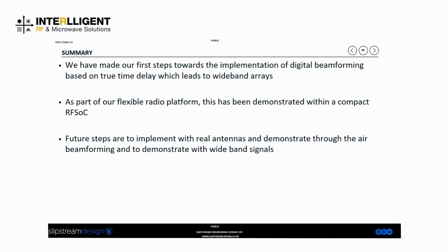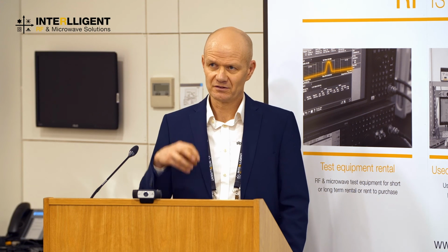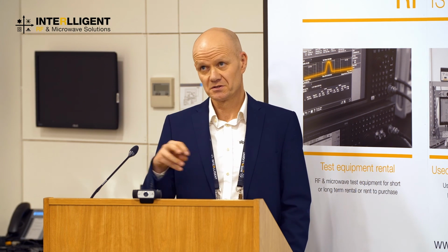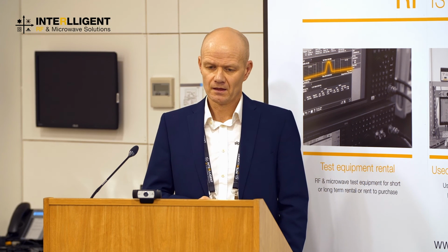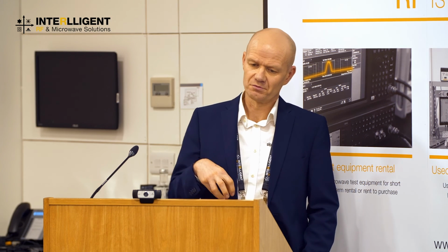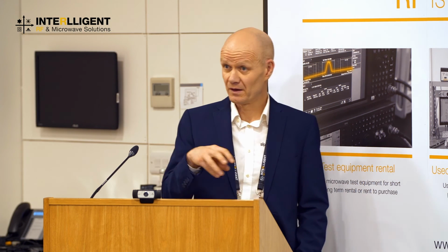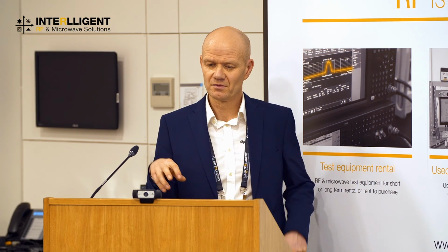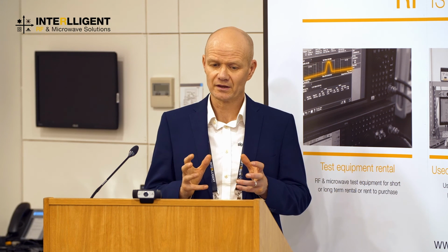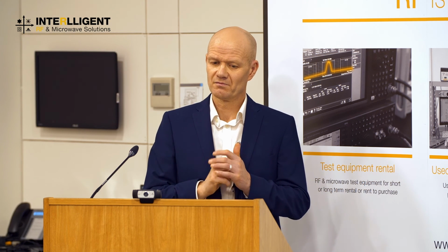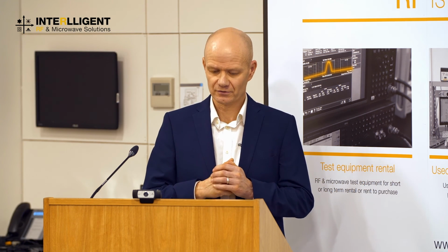So in summary, we've made, I would say, our first steps towards implementation of digital beamforming based on true time delay, which helps lead towards this wideband array idea. And as part of the flexible radio platform, we've demonstrated that on an RFSoC device. And then future steps are to implement that with real antennas and do some actual through-the-air beamforming to demonstrate this with wide instantaneous bandwidth signals.